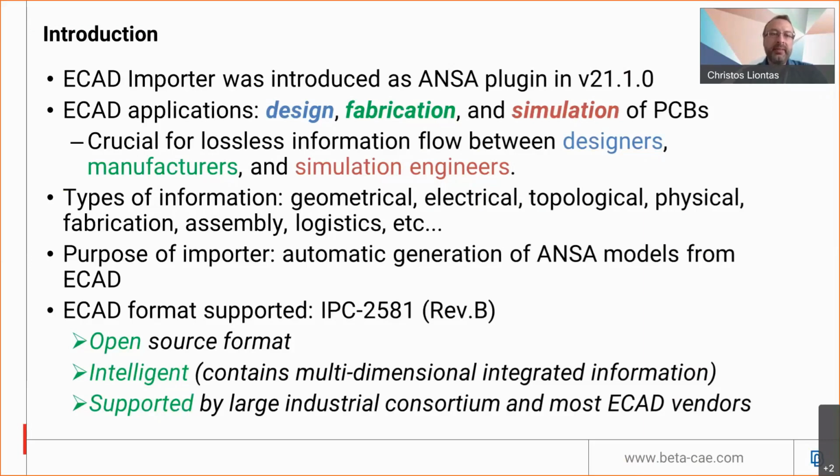The ECAD format that we have chosen to support is the IPC 2581 revision B, which has been chosen because it's an open source format. It's intelligent, so it contains interconnected multi-dimensional information. And it's supported by a large industrial consortium and most ECAD and EDA vendors.